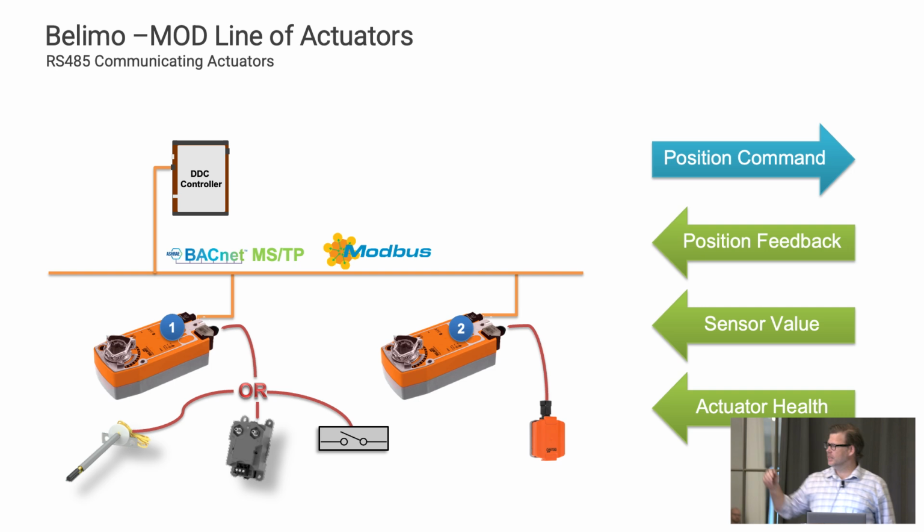Okay. All right, so we call it feedback for free because you're already connecting to it, and you get all this information from this device. So if a damper gets stuck, someone clutches it out and forgets to release it, this is some of that information that could be really useful when troubleshooting, like when zones are over temp, or feedback and set point aren't matching. These are just little pieces of information that you get by connecting these devices.